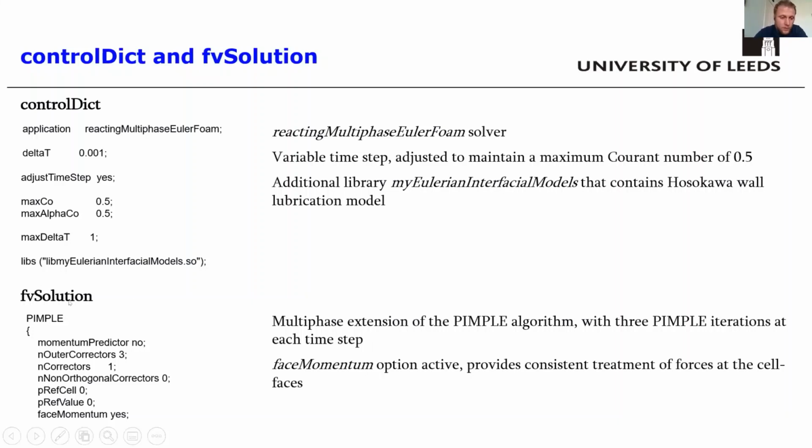And the other thing I want to talk about is this phase momentum option, which is a slightly different formulation of the balance equation that provides a consistent treatment of the forces at the cell faces, and is known to have some benefit in some particular conditions.